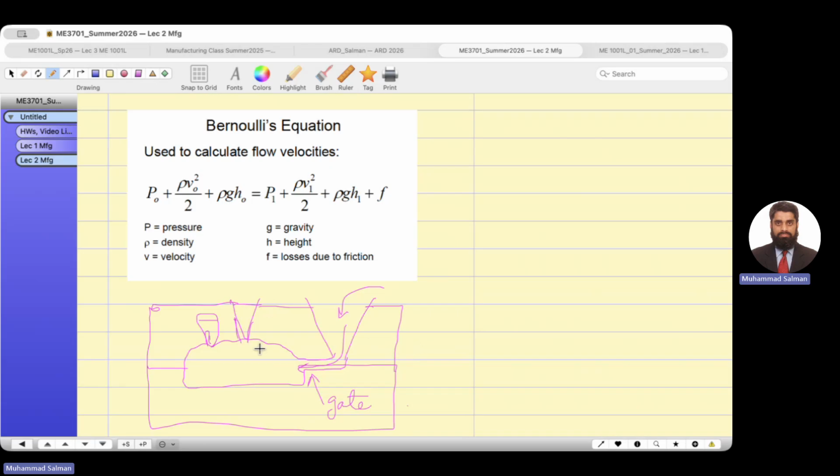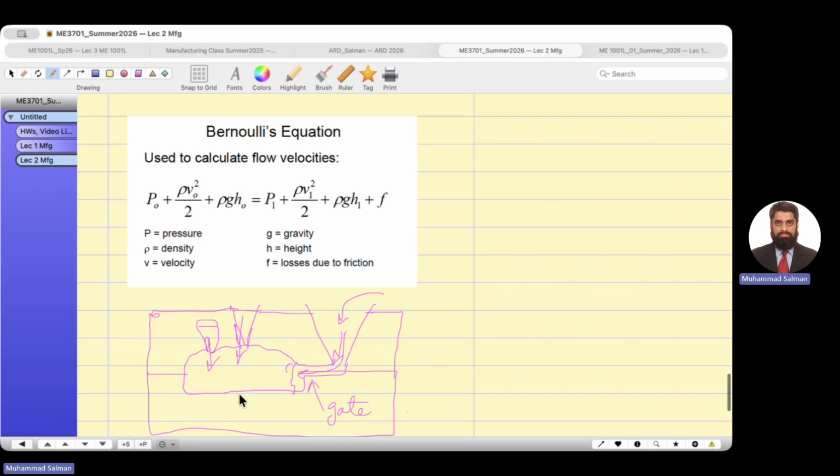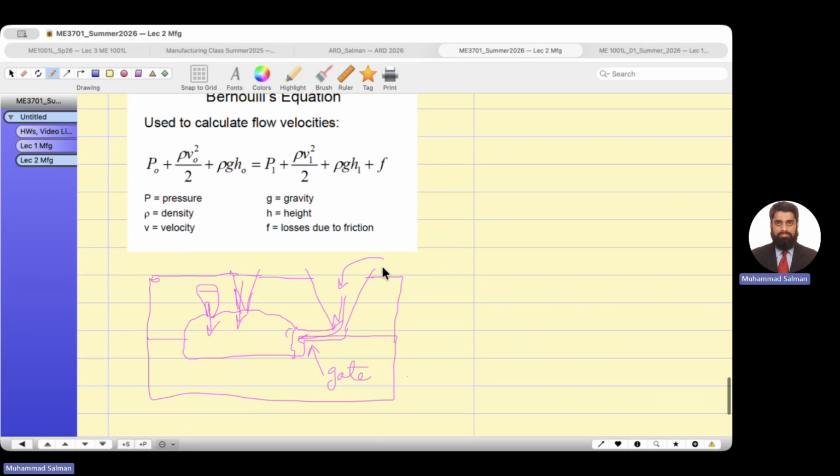You know why do we provide risers? Because the solidification process shrinks the casting, and then that shrinkage losses are filled by the riser molten metal, because it starts solidifying here as well, so it cannot compensate that shrinkage losses. So those risers, they are very helpful, blind risers, open risers, to cover the shrinkage losses. You see my point?